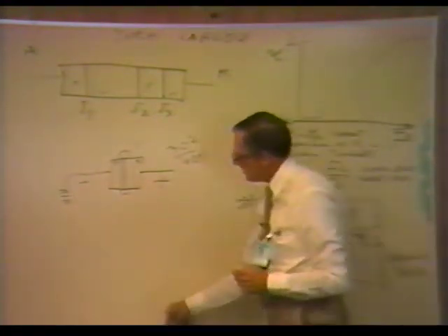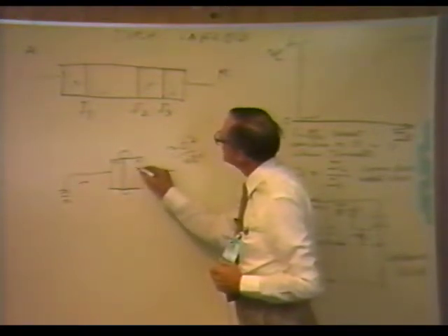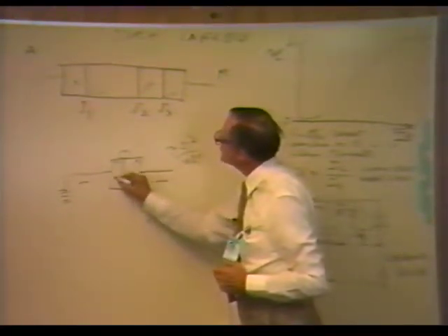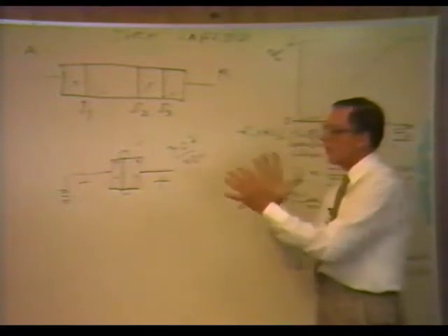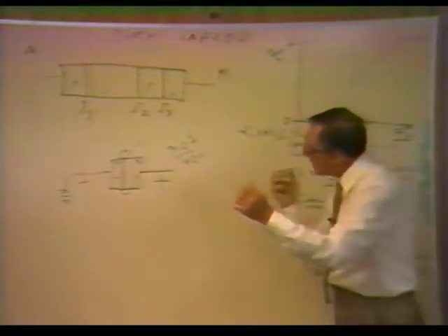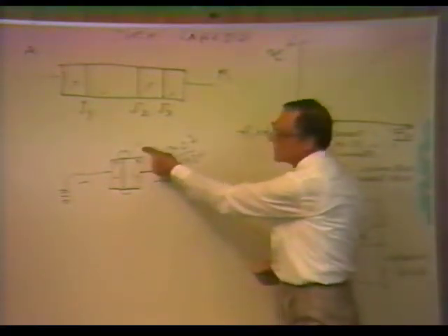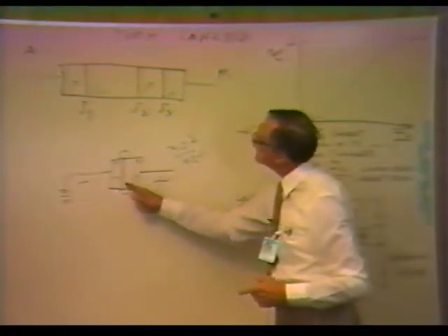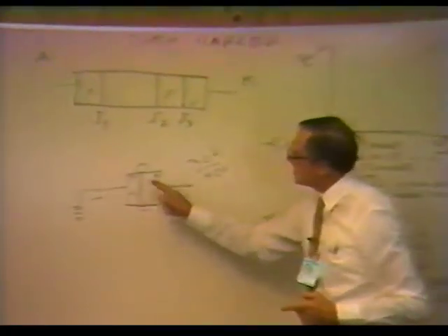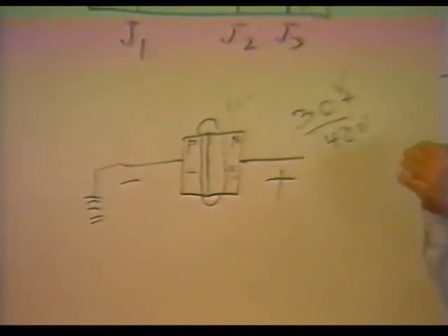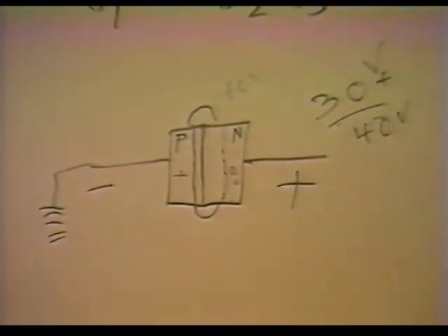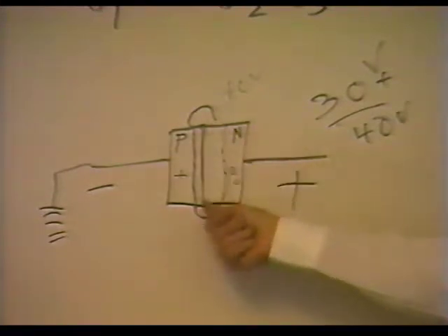And the minority carriers, which are holes that are over here, and electrons that are here, the minority carriers that are always in there somewhere, motivated by the very high voltage, start flying up to the junction, and they start running into the lattice work and knocking off the valence electrons that are in the structure.